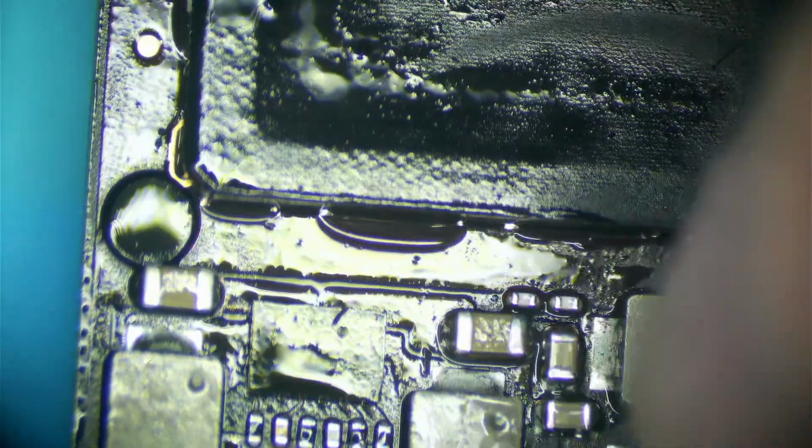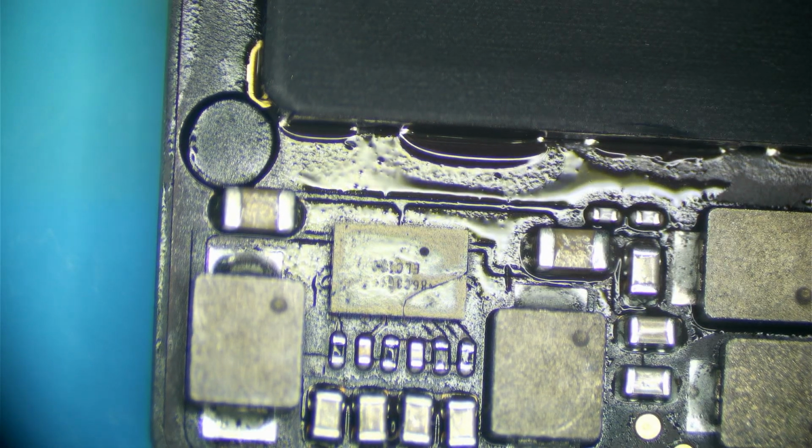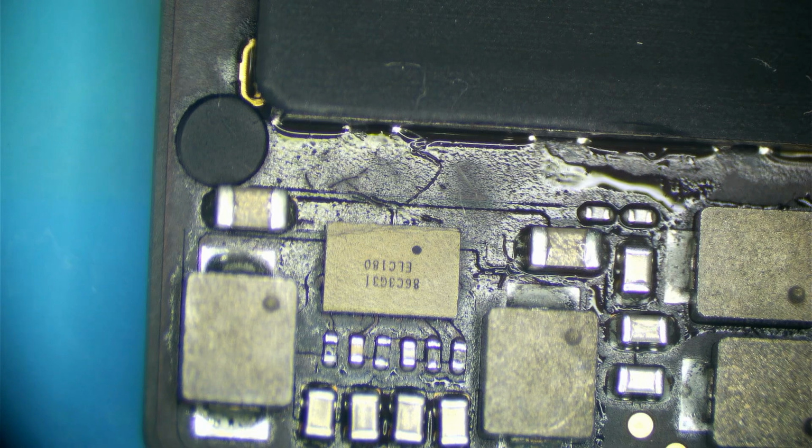So I think what we're going to do on all these A1990s is start conformal coating these areas to prevent the future failure of this one chip if it gets dusty. So just want to make sure it's really clean right here, and I'm just going to go ahead and put a little dab of conformal coat on it just to prevent that possible future failure happening. We're actually going to do that after we dust it there, so we'll be right back to put that on.